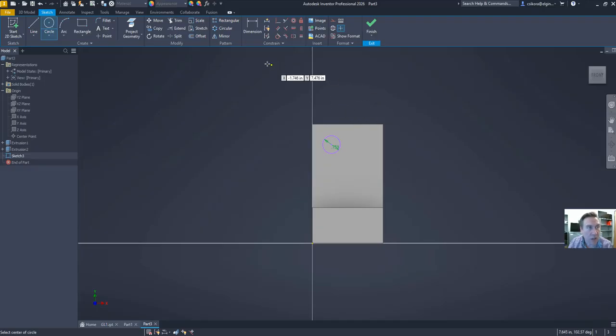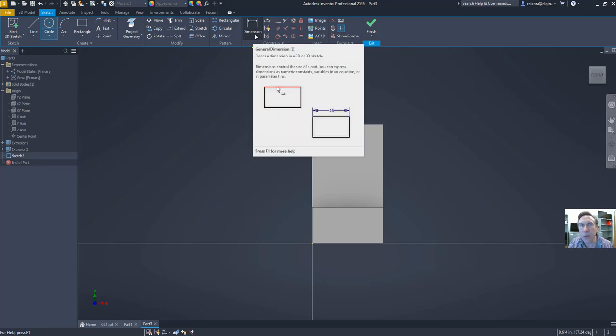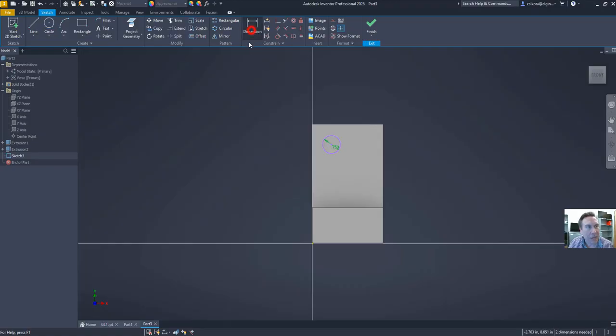Now to position it, we're going to use the dimension tool that's up here. See Dimension? You could also use the fast key, which is just D, but go to Dimension. Now select this point, and many of you have already gone through the segments where we hand sketched this. We talked about extension lines and dimensions and such. Use that same philosophy when laying this out. So click on the point and then the left edge. Move your pointer straight up and get the dimensions centered between the arrows. Click and type in 1 and hit Enter.